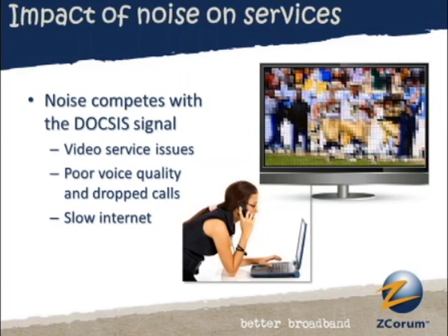It really depends on the scenario. You can actually have both kinds of situations. It's certainly very possible where you can over time find that your noise floor keeps creeping up, and you look at it and go, well, it's only going up a quarter of a dB a month, but you let that go for a couple of years, and then suddenly you really don't have a lot of margin between your cable signal, your DOCSIS signaling, and the noise floor, and now your SNRs are bad. You can also have that fall off the cliff kind of scenario.